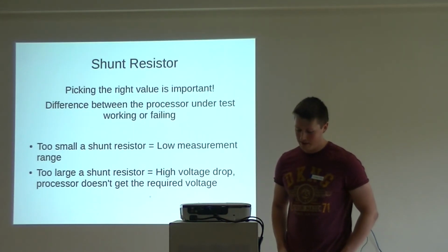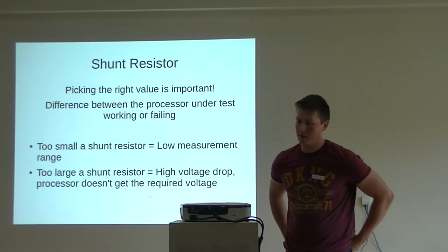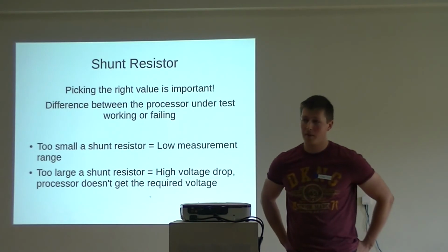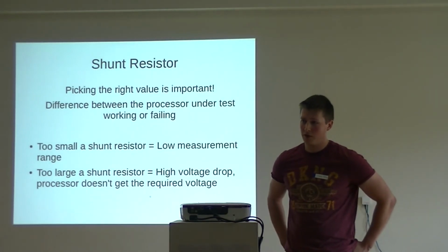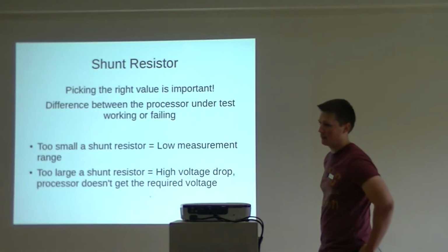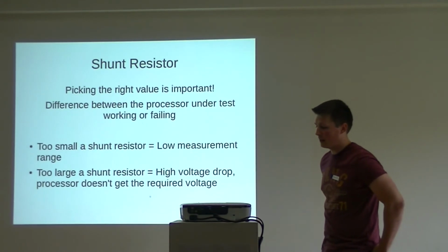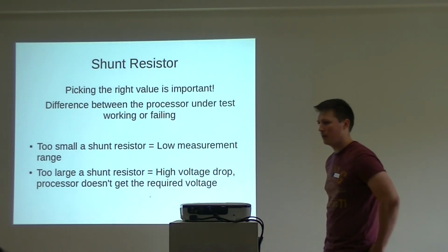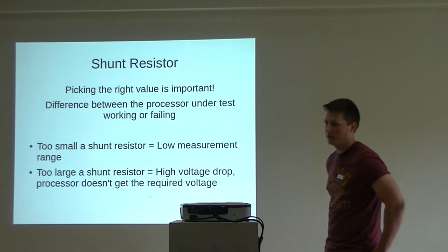It's challenging. There are high side differential current amplifiers that we use, specifically designed for this job of working with high common modes and amplifying such small voltage drops. They can be quite noisy, but because we can take 6 million samples per second but can't send 6 million samples per second, we take several samples, average them out, and then send that sample. So we do averaging as well, and that seems to give us a fairly good result, which is consistent. I think we're getting what we expect.